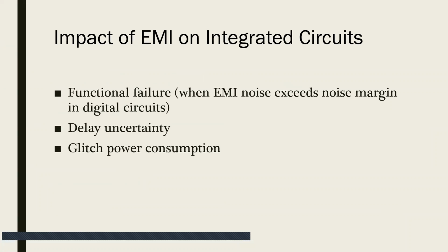Secondly, it will cause delay uncertainty, and thirdly, it will cause glitch power consumption. So basically, because of those ringing effects and resonance, the glitches will have extra power consumption.